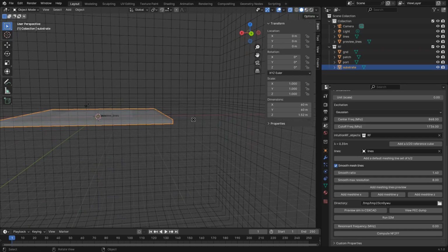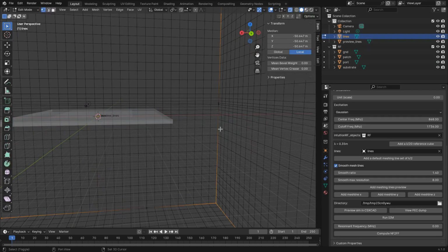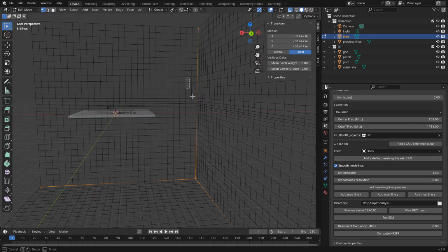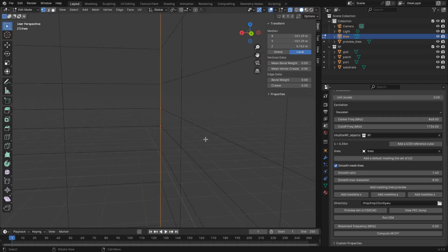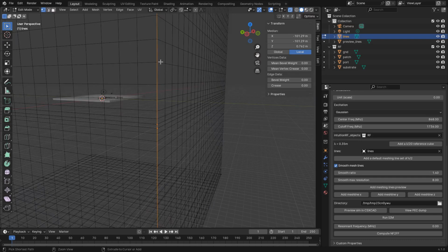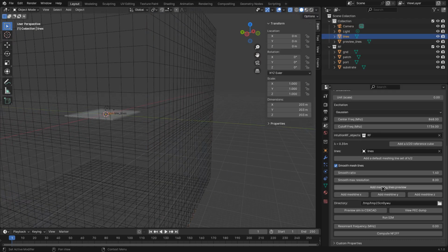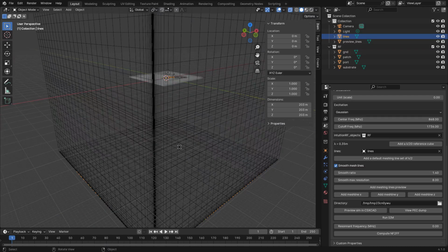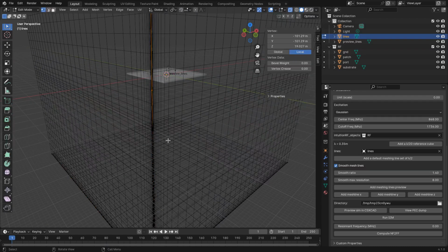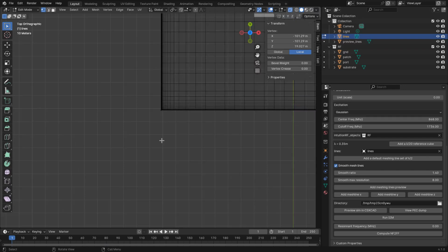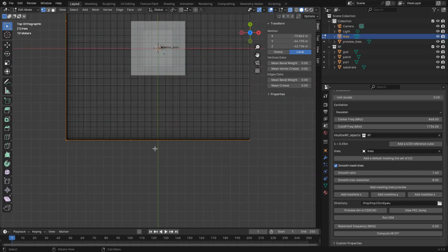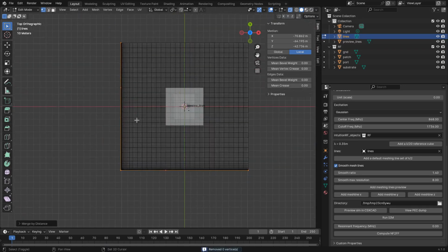And what happens is it adds vertices into this lines object. So you see we have new vertices here. And if we subdivide this and add new vertices, we get new meshing lines. Sometimes we get this kind of artifacts. It usually means that vertices are overlapping or that you have some weird scaling happening. So let's fix this.